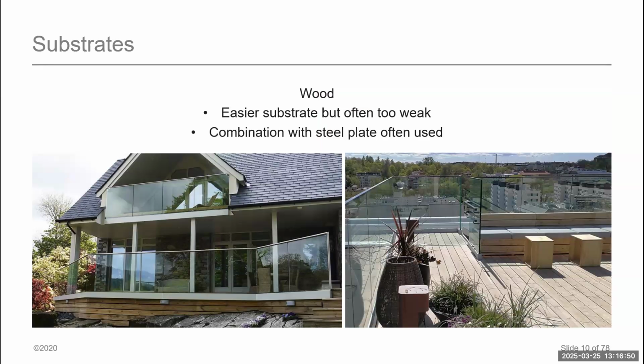Another thing that we will see is wood. I would say this is more residentially focused. Wood is one of the most challenging to attach to because it requires an extreme embed depth, because we need to use some type of anchor like a GRK or a structurally rated screw that will go in there. And we'll talk about this as we move into base shoes and adapters and so forth. With a base shoe, for example, which is attached every 8 inches at 42 inches high, we will see a transfer load somewhere around 2 to 3 kips, or 2 to 3,000 pounds per anchor.